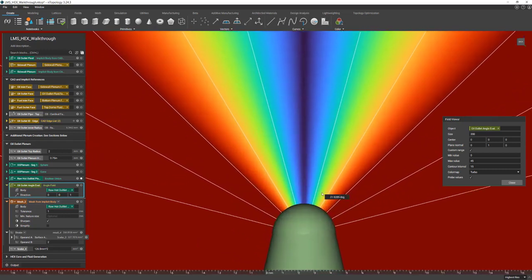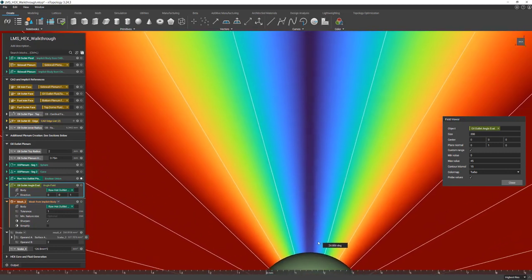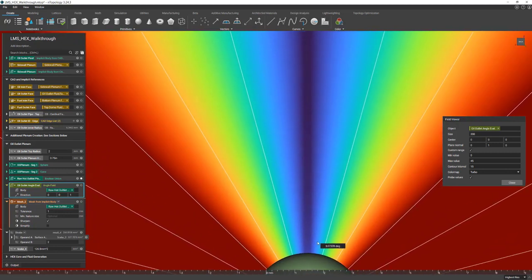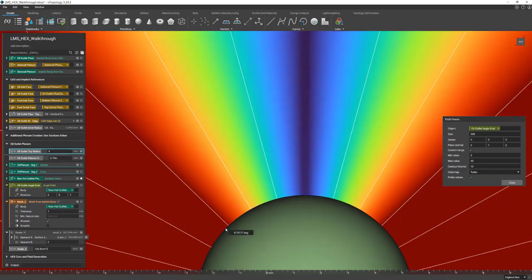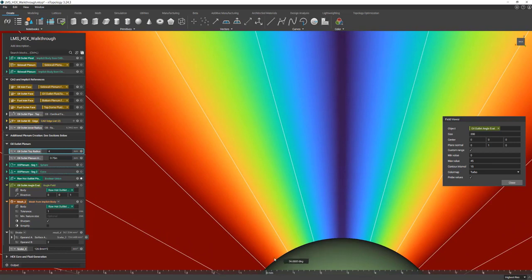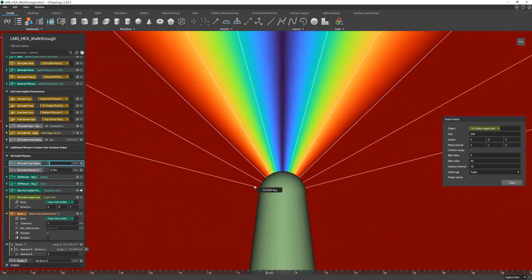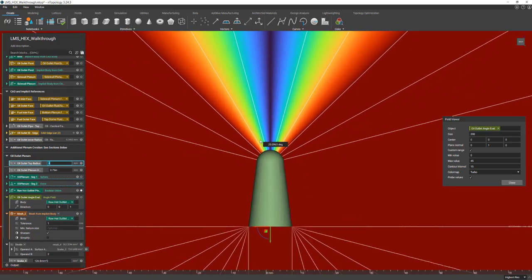And at this point, at this line and over here, we have our 45-degree or less angles. So we can do a quick evaluation. We might know that we can have an acceptable overhang, let's say, of less than 3 millimeters. So we can stick with the top radius that we have. Perhaps this was set to 4, and we look at where we have our 45-degree angle now, and our overhang is from about 0 millimeters out to about 5.6. So we'd want to potentially start to decrease this radius until we've met this overhang constraint.